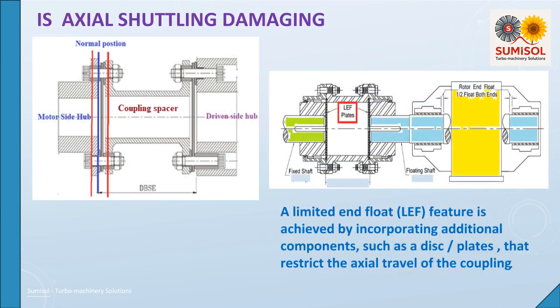If the axial position of the motor at rest, mechanical center, is different from the magnetic center, the rotor of the motor may move axially to the magnetic center when running without load. This is a low-frequency phenomenon and normally present in two-pole electric motors. A limited end float sleeve-bearing motor, for example, floats as the rotor hunts for the magnetic center of the winding. It is, therefore, necessary to use a coupling with limited end float. Couplings are used in such cases to avoid movements in the driven shaft.